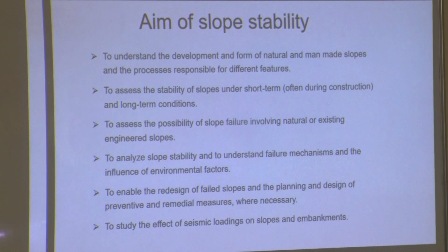Then the last parameter we generally consider in mining for stability of slope is the dynamic load. This dynamic load generally comes from the vibration, the heavy amount of vibration that occurs on a daily basis in the mining, and also if the zone is very earthquake prone, then there is a possibility that it is always experiencing some kind of seismic waves regularly.